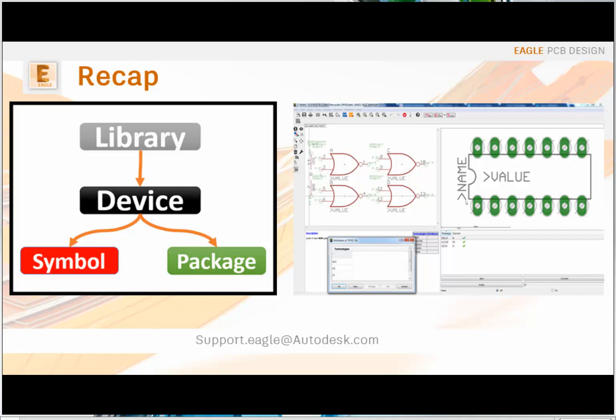Now there's one distinction that I want to bring up here: each pin has a visible parameter. In other words, I could have it show the name of the pin as well as the pad assignment. It could be both, it could be only the pad assignment, it could be only the pin name, or it could be neither of them. A very useful tool, but many times the naming of the pin cannot be moved around. So for those, you may want to disable it and manually put it in using the text command.